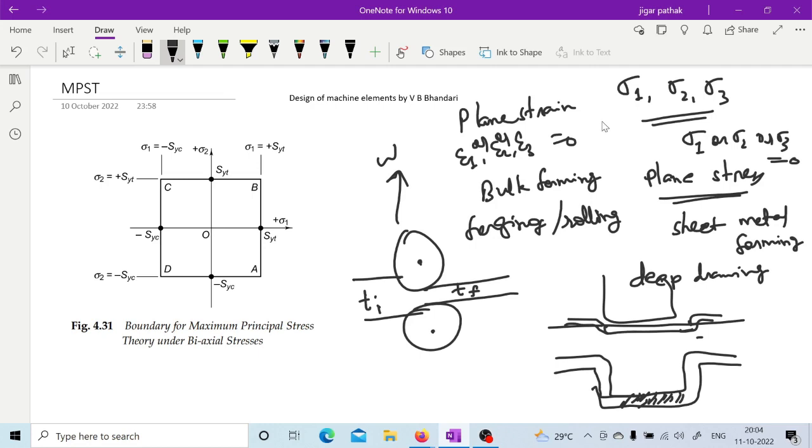In punching, I mean the sheet metal punching that you have drawn, there is a shear stress on the ends, isn't it? It will be through that shear. Yeah. So the shear stress is actually no. Sorry. In case of deep drawing, you will not have any shear, I guess. It is biaxial stretching in case of deep drawing. Shearing will be there when you go for blanking. In blanking operations, you will cut your material through that shear. In case of deep drawing, it is biaxial stretching.